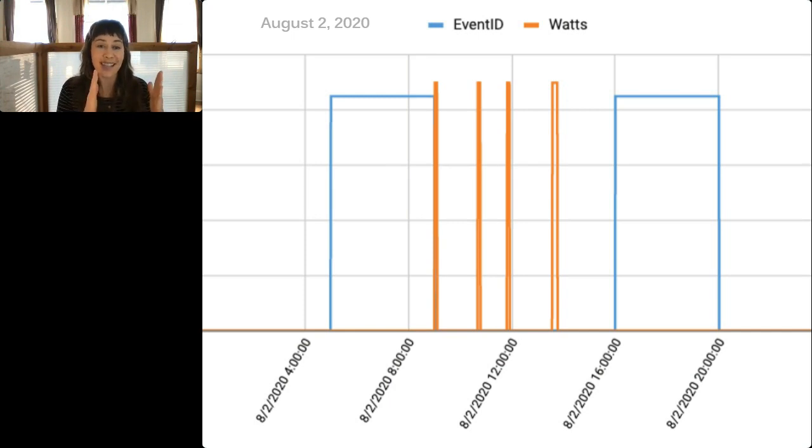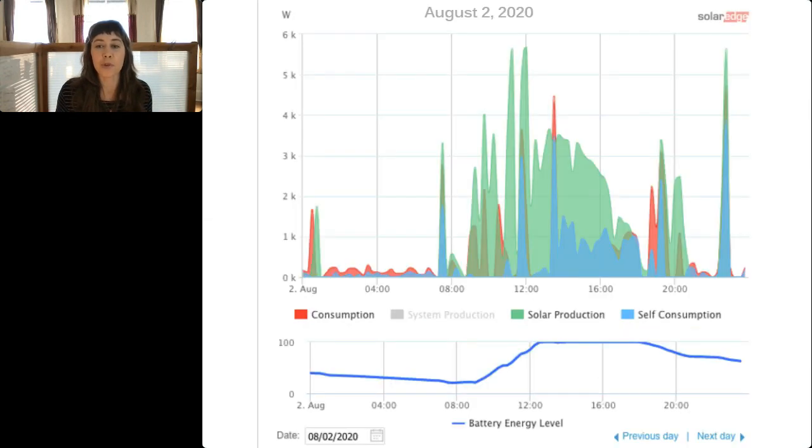Those shed commands were extended daily beyond the typical demand response period to try and make the snapback of the water heater happen when this was solar rich. Now, this is in Oregon in August. You can see the snapback happening here with the water heater, and you can see how those align with the overall solar profile of the building, and that we've taken those spikes out of the period where you're having the morning shoulder in the Pacific Northwest. So it's solving a grid problem, and it's also sopping up that excess backfeed from the solar.